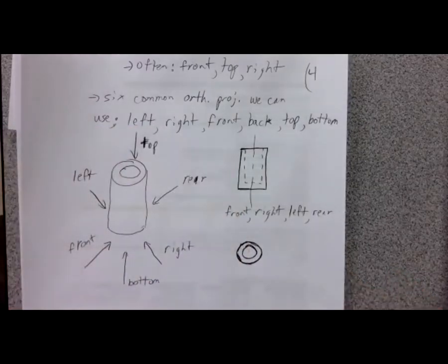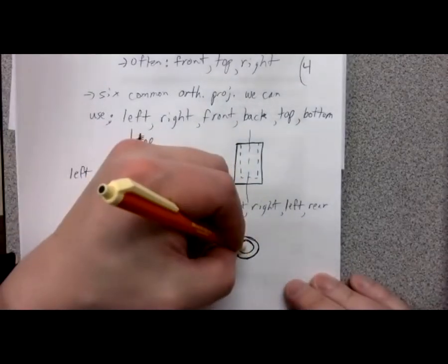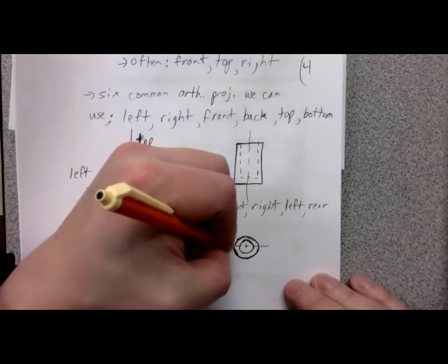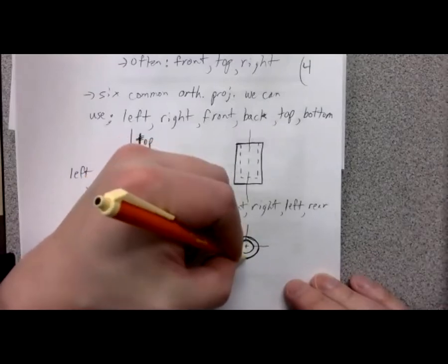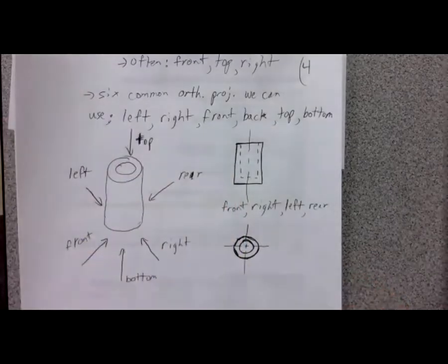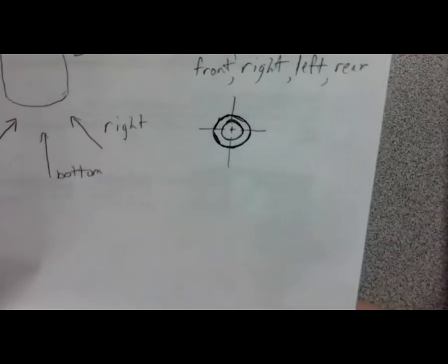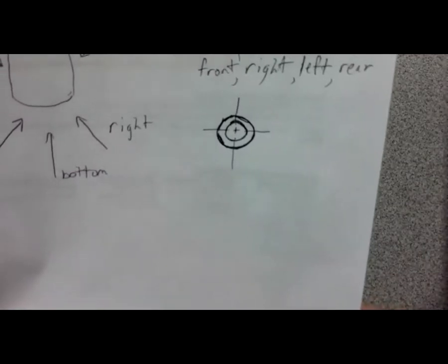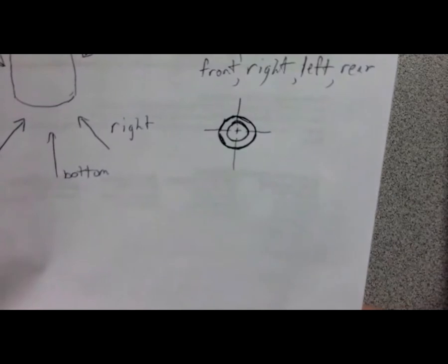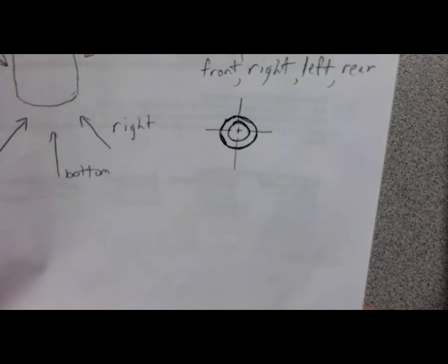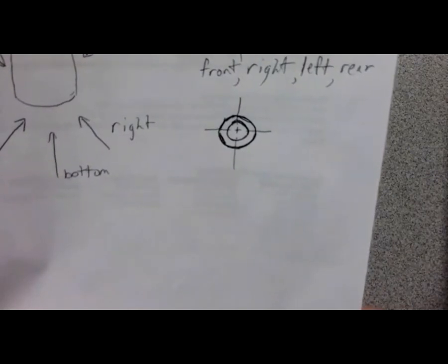Get a little more detailed. I'm just kind of quickly drawing for demonstration purposes here, a rough circle. It doesn't have to be pretty, but I went back and made those obviously visible lines because I'm going to put now thin lines designating symmetry. So a common thing you can do when you're dealing with a circle, if you put the short dash of your center lines intersecting at the center of that circle, that's an easy way to define the location of the center of that circle.